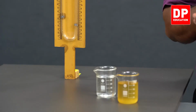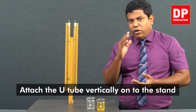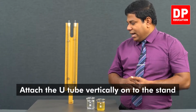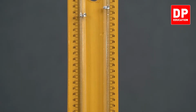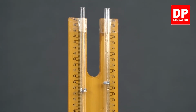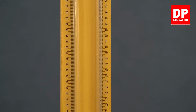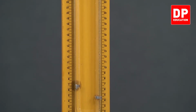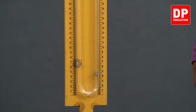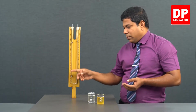Students, you can see I have fixed the U-tube on a vertical plane. That is essential. When you are fixing it, make sure it is on a vertical plane. And see, what we are going to do here, we will fill this with water, right, to a certain level, maybe up to 15-20 centimeter, depending on the length of the U-tube you have. I have one up to 45 centimeters. So, approximately to half of it or a little less than half of it, I will fill this with water. So, the water will remain in the bottom part of this U-tube.